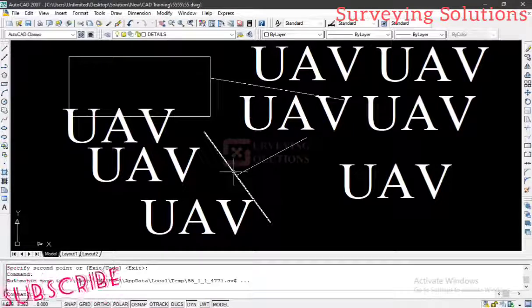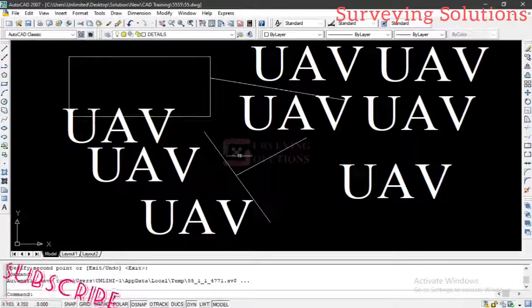Same thing when you want to trim, there will be an intersection between the two objects. So you click the base object, enter first, then you click on the other part of the object you want to trim off. So the applications are dependent on what you have at hand. But this is how you can use those commands on AutoCAD.